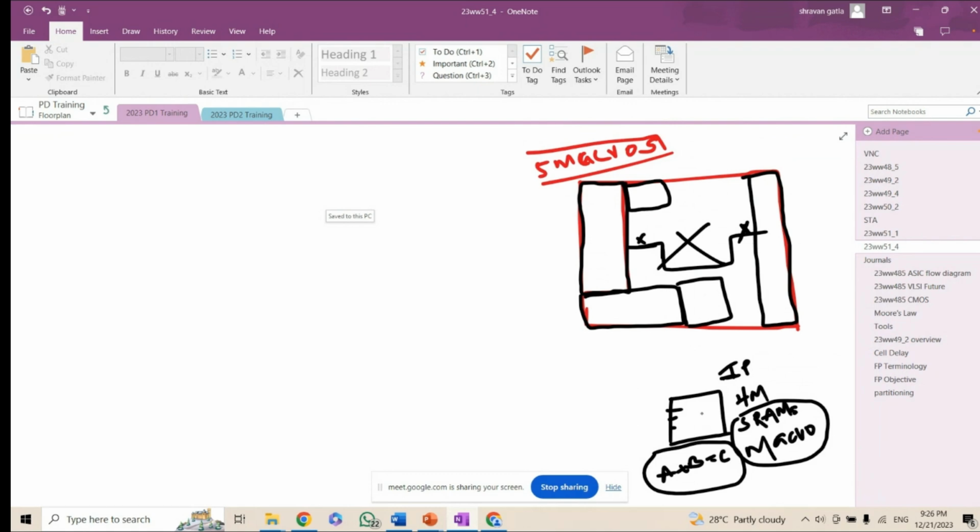If someone else did this, when they were doing it, they will also have the IO ports, and they will have the standard cells inside. They will do all the routing, and they will make sure the clock tree is built nicely, and everything, and they will give it to us like this, and we just use it. That's why we will have some routing blockages inside the macro.